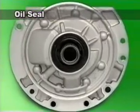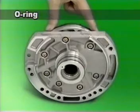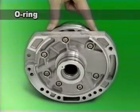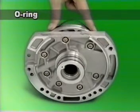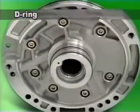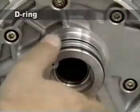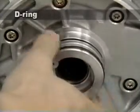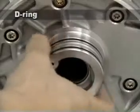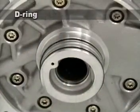Check the appearance damage of the oil seal and O-ring of the oil pump, which is connected to the transaxle case. And check the appearance damage of the 2 D-rings of the oil pump installed at the connecting point with the underdrive clutch. If any of the 2 D-rings is damaged, oil supplied to the underdrive clutch leaks, causing difficulty in forward driving.